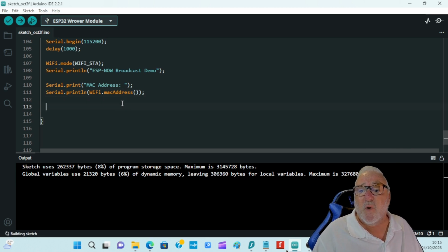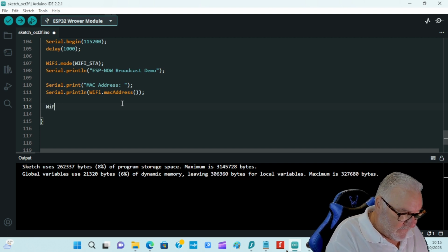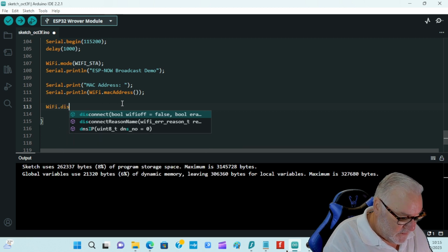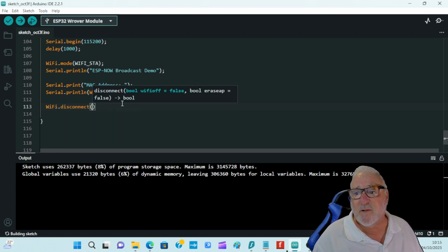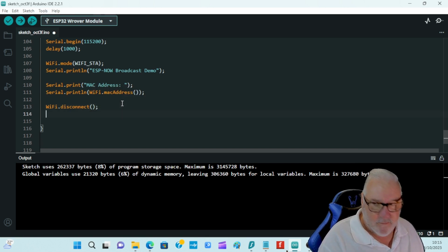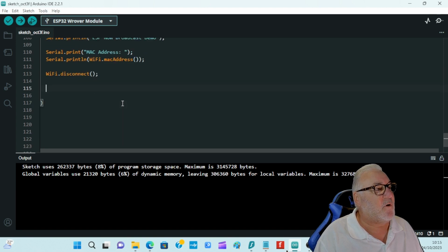Now we need to disconnect the WiFi. WiFi.disconnect, brackets on, brackets off. Come outside the bracket, semicolon, enter. Initialize ESP-NOW. Come down a bit, guys.